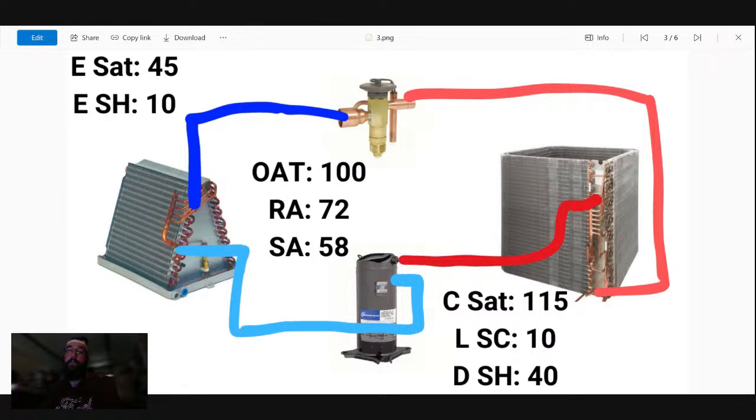I've seen a lot of times where it may not be super obvious that there's a coil issue or the coil's dirty. The whole top section of those condenser coils is the oil cooling circuit, so it's imperative that the higher end of the coil is really clean for that purpose. Those would be the three things I'd want to look into.